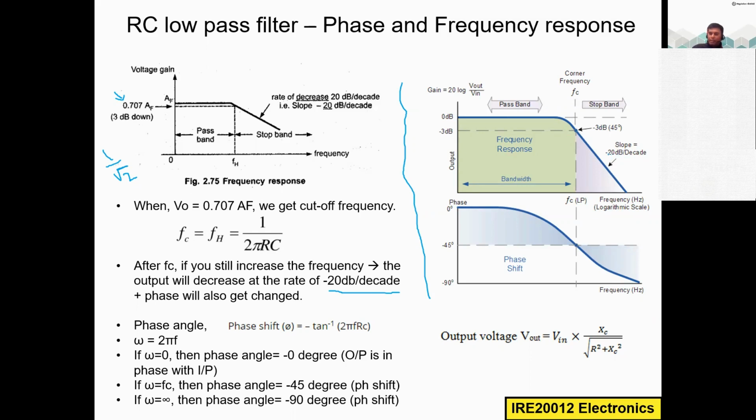As I already told you, the voltage gain is measured in decibels, dB. So this is the formula for the gain calculation. This is also a standard one used in all filter designs. So here it's falling down at minus 20 dB per decade. You know what decade means. This is with respect to the number 10. In practical life we also use this word decade, for example, the last decade I was in another country.